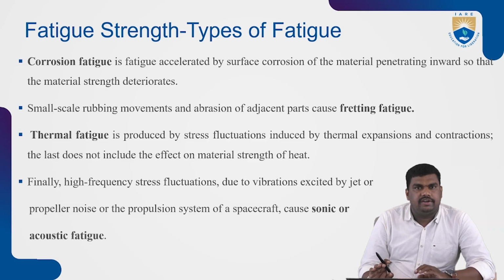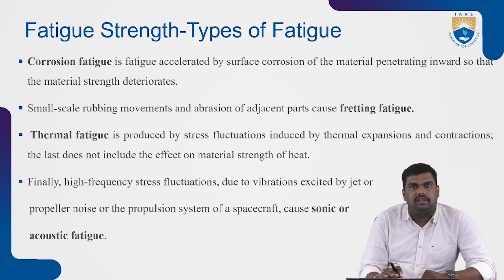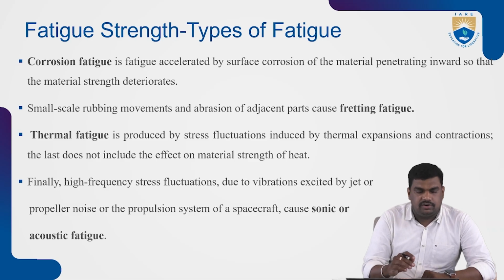So in corrosion fatigue, corrosion happens on the surface. If the surface is not smooth and has undulations or notches, we know that it leads to stress concentration. So the fatigue will happen.